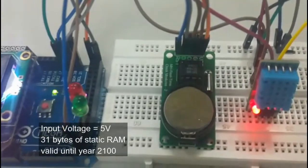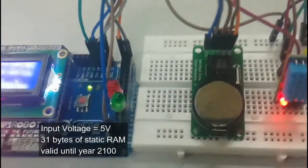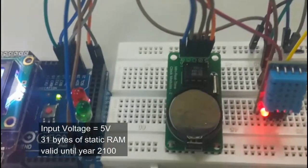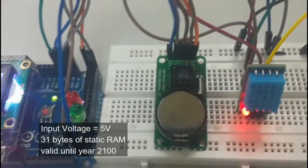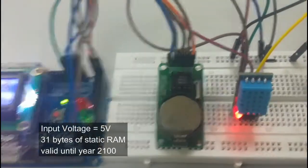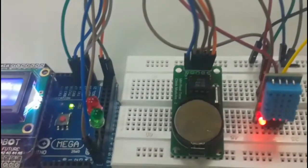Its input is 5 volts. It is used in our project to save the value of the time and date. Basically, the RTC DS1302 has 31 bytes of static RAM, which is used to store the data.